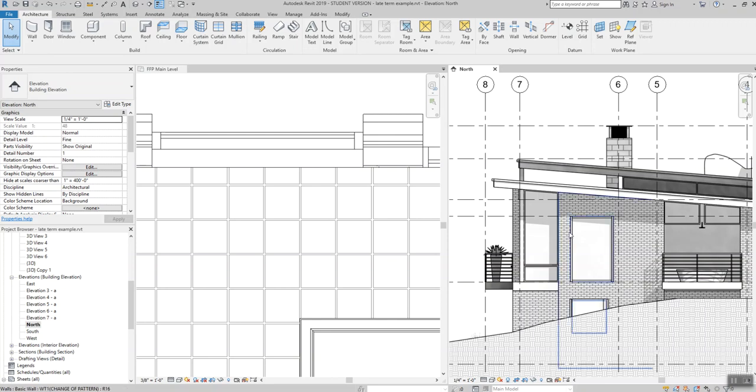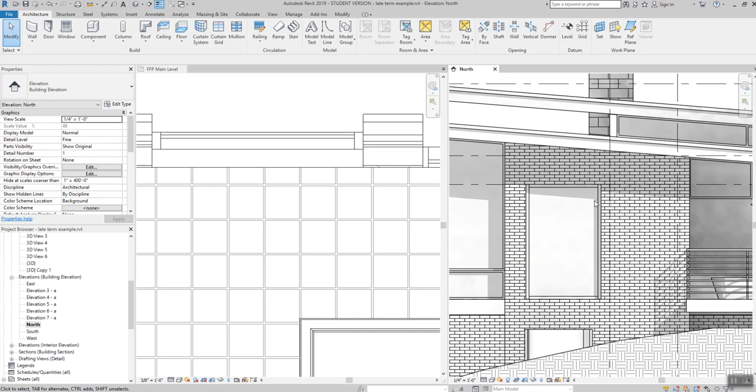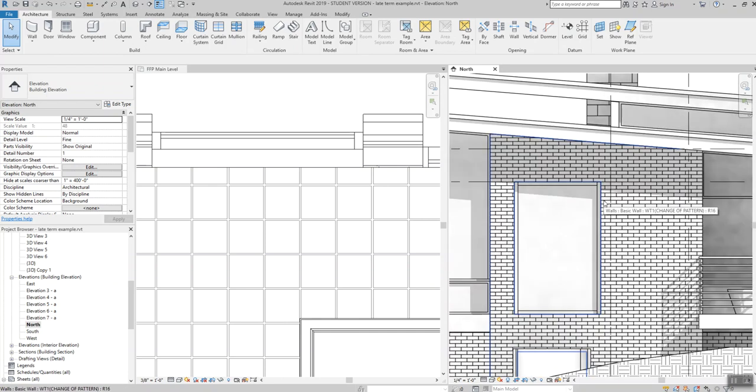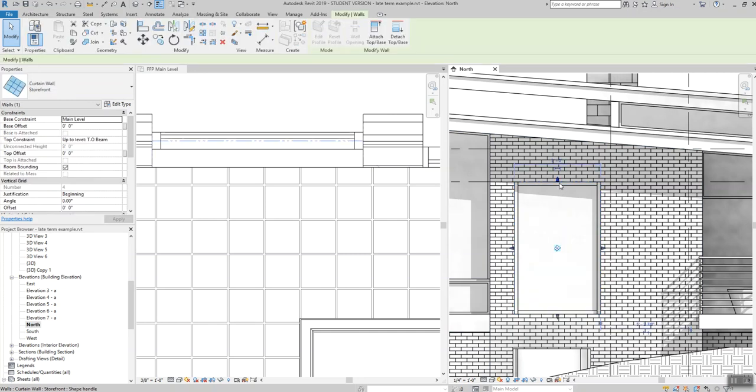Okay, I'm going to select it, and I hope that the storefront video that you watched made it pretty evident that selection of storefront is kind of the hardest part of creating storefront because there's so many pieces attached to it. I'm going to tab till I see that dashed blue line all the way around my storefront, and when I click then, that selected the entire storefront piece.